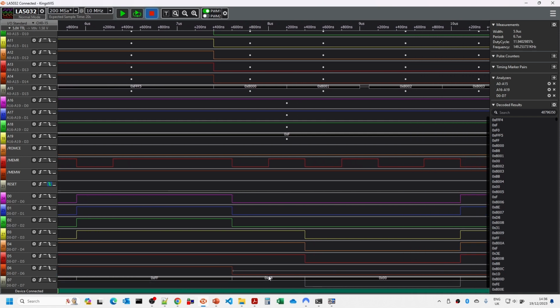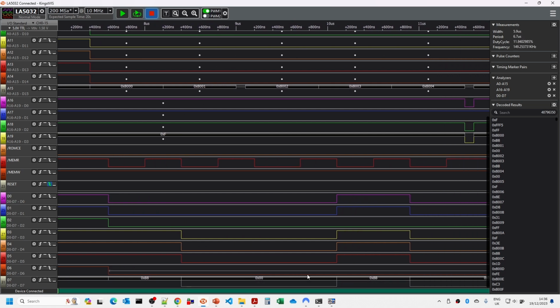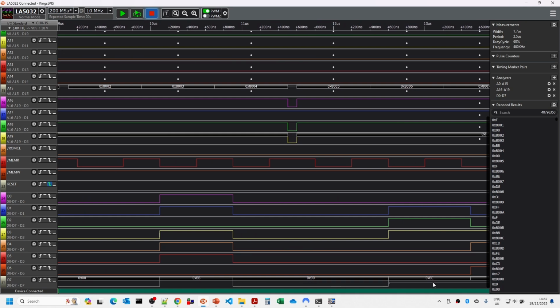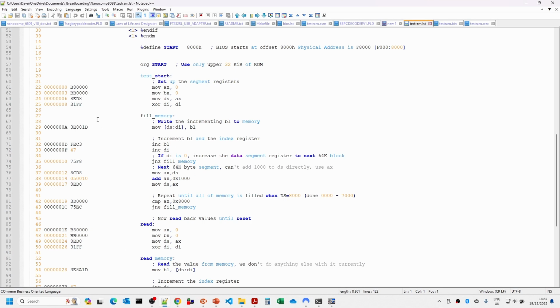There we go, we've got BB 000. Now you see this is about twice as wide, so it means there are 2 00s here, because you can see we've got 2 reads here, and each of those is 00. The logic analyzer only shows where there's a change in the values. Then we've got BB 00, then ATD8. So if we go back to here, ATD8. It looks like the code has gone to the top reset area and then successfully come down here.